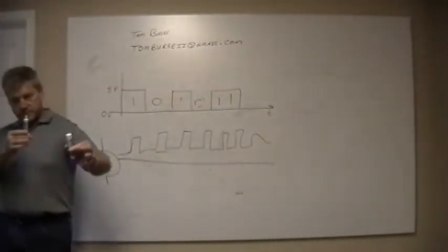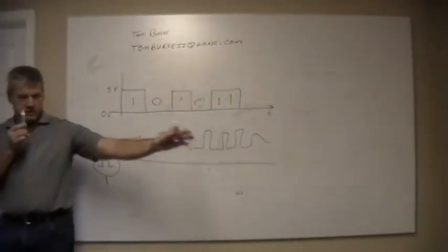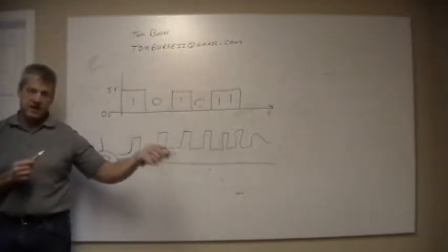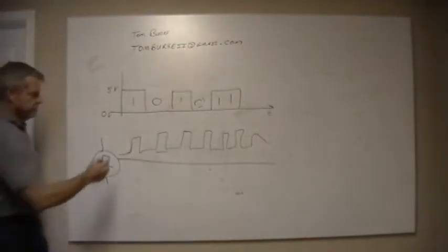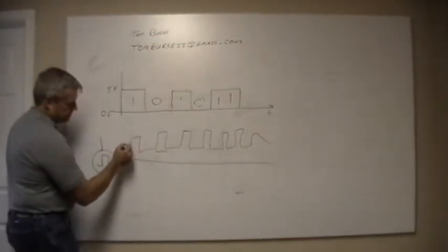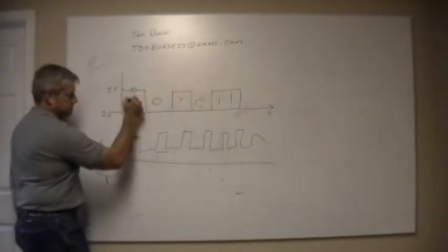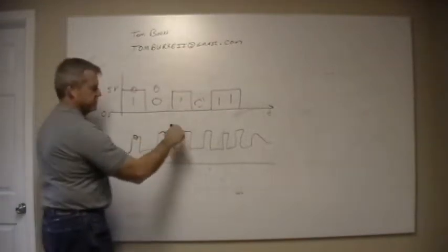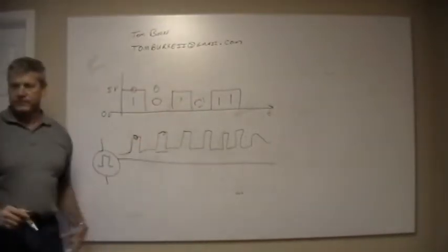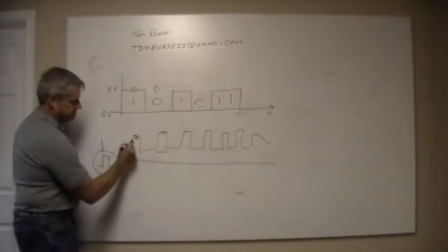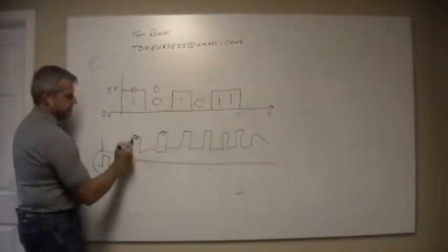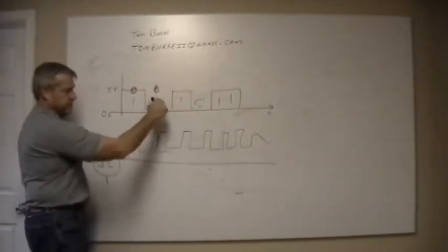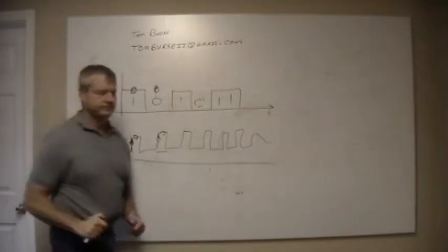And when two devices that are some distance apart talk, somehow they supply information about the clock to each other, whether they actually supply the clock or they embed it in the stuff that they're doing, so that you know that whenever this is high, I sample there, sample there. So I know that when this one happens and that one happens and this one happens, I know specifically which one's which. The truth is we actually sample on the edges usually. So these are offset a little bit, so try and set the edge up to happen right here in the middle of that bit time.